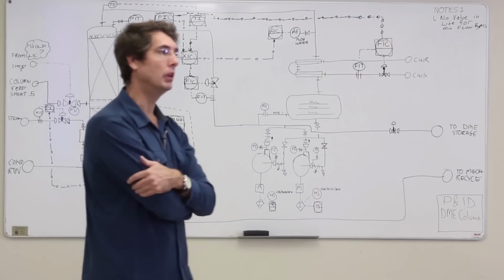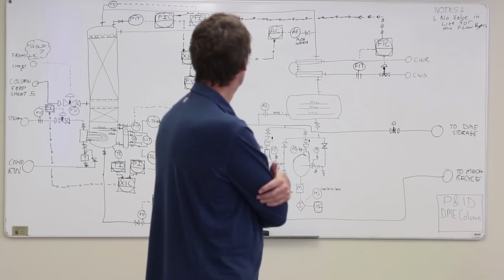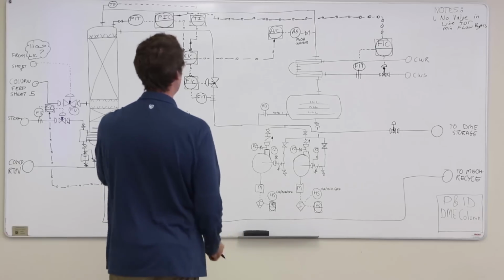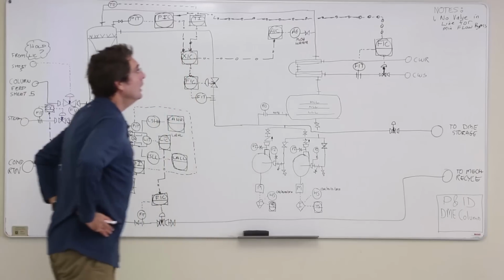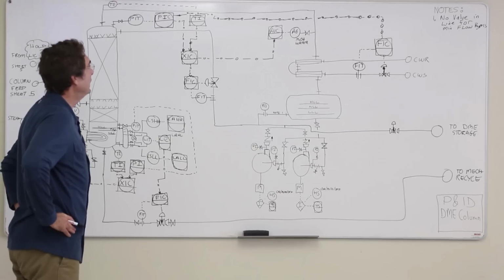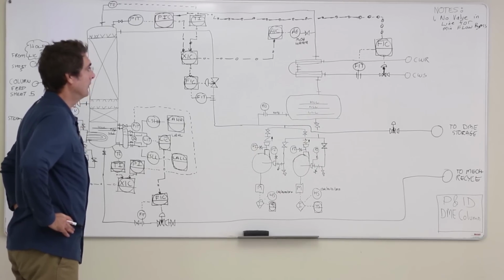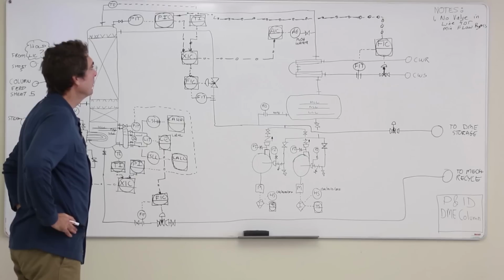temperature control, composition control. I was just wondering, if you don't have another control valve, then you're not going to be able to control the temperature. If we don't have a control valve here... Well, yeah. I think right now you've got pressure, composition, and I'm assuming you're going to put in a level control. Yeah. That takes all of your control valves that you have currently drawn in. Yeah. Which means that you're no longer controlling temperature directly. So it might be better to do the pressure system as you said, put a control valve on the feed into the condenser, and then keep that control valve on the cooling water supply there, but have that tied into the temperature.